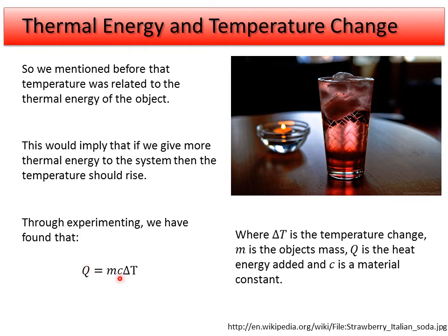If instead of using ice we change to water, well then water is going to have a different material constant, a different specific heat. So you have to be careful to make sure that you're using the right material and the right phase for this, and that'll get you towards the right heat that you need. And even that is not necessarily true. These specific heats can vary slightly based off of the temperature. So depending on how accurate you need to be, you may have to use different values of C.